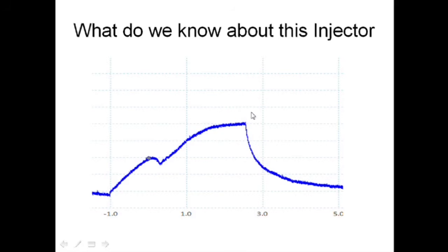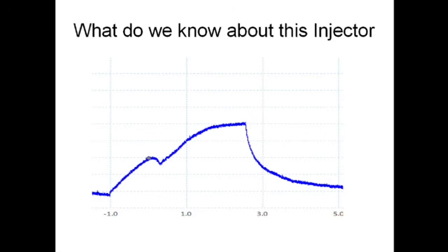I don't have any measurements here, so I can't tell you the duration of the time of the solenoid or the injector. I can't tell you the amount of current flow, but I could measure and provide that information. But right now I'm just focused on what do I know about this injector, or if it happened to be a current ramping waveform of a solenoid, I know that it opened. That little bump about halfway up the current ramp is a dead giveaway that the solenoid opened.